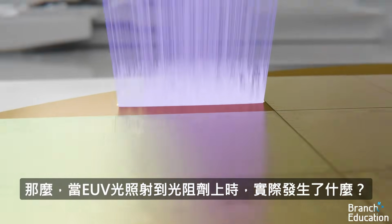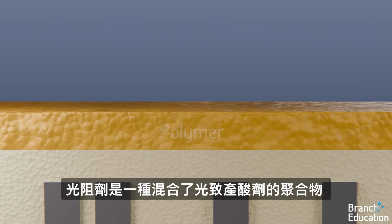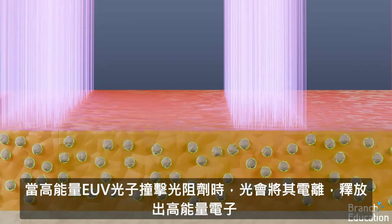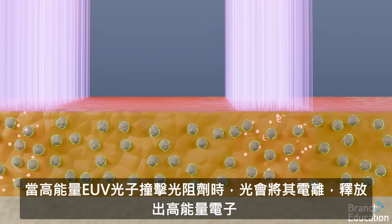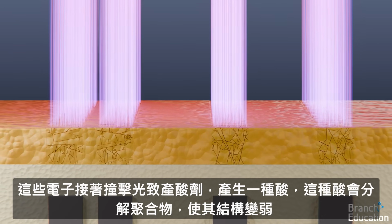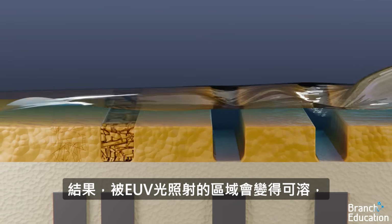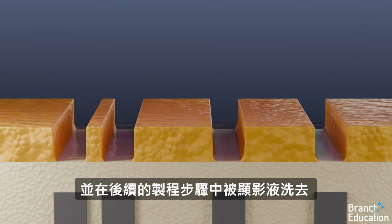So then, what actually happens as EUV light hits the photoresist? Well, resist is a polymer mixed with a photoacid generator. When high-energy EUV photons hit the resist, the light ionizes it, releasing high-energy electrons. These electrons then hit the photoacid generator, producing an acid that breaks apart the polymer, making it weaker. As a result, the areas hit by the EUV light become soluble and are washed away by a developing liquid in the subsequent process step.